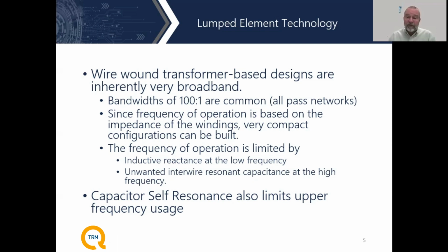Another component that does limit what we can have for a high end on these devices is capacitor self-resonance. That is also an important parameter that we have to watch out for as we are designing these sorts of lumped element technologies. So a big advantage of lumped element technology is that it has extremely broad bandwidths.